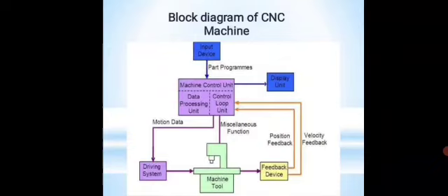Then how does the CNC machine work? In a CNC machine, a dedicated computer is used to perform all the essential functions as per the executive program stored in the computer memory. The system directly commands the servo drive to drive the servo motor and other output devices like relay, solenoid, etc. to initiate operations such as motor starting and stopping, coolant on and off, tool changing, pallet changing, etc., and other miscellaneous functions.